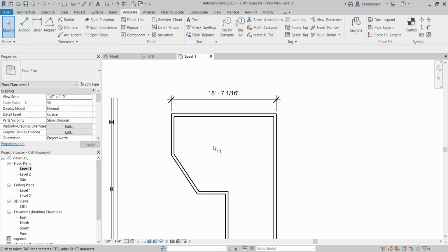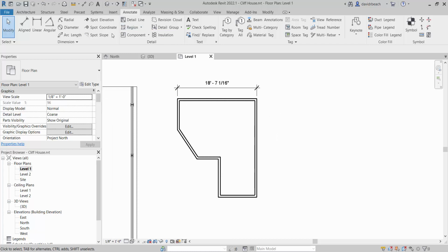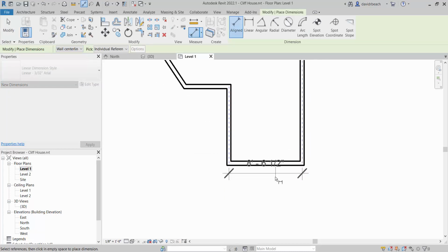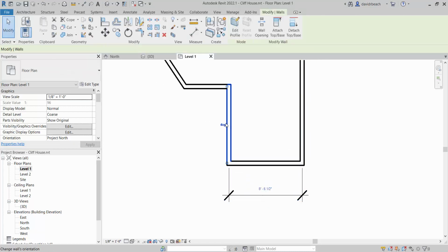Okay, because if you go someplace outside of our region, you might want to do this a slightly different way. But here regionally, our contractors, the people that are going to be building your designs, most of them loathe centerline dimensions. Okay? So let's think about why. If you are out in the field and what you have been provided is aligned wall center lines, this to this, and it's placed here. How do I place this wall and this wall if I'm in the field?